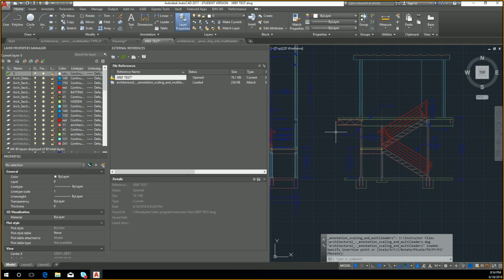It's right there. So this is still the snapshot memory of the last time you inserted this, the last time you defined the insertion. So this will have whatever you had at that moment until you decide to go browse or to redefine it. So let's say you've done changes now. You want to redefine it, so you want to update anything that's been modified. That's what you would do.